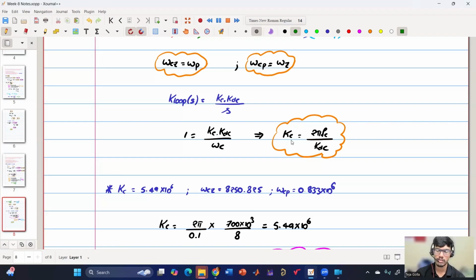As well as in simulation, it will work, but hardware will have additional delays, like op-amp delay, and then op-amp saturation. If you have high gains and the op-amp saturation is limited, the op-amp might get saturated and the converter may become unstable. In simulation there is no saturation.